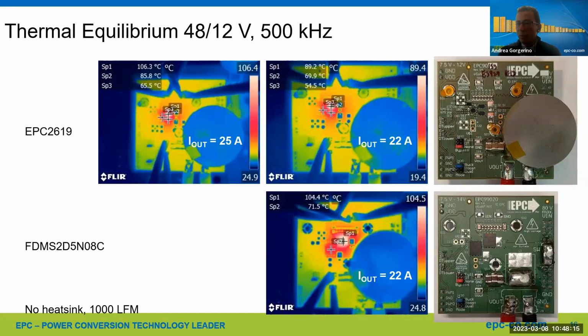They're much smaller in terms of all the capacitances, for example, which means you end up switching much faster, and the gate part. So I think the first challenge is just making sure you select the appropriate gate driver and controller. I already mentioned that, right? So you have to make sure you select the right part. And then it's layout. Layout is very important, because yes, you can make a bad layout, but then you're going to slow it down, and then you might as well use a silicon FET. So you want to make a good layout, and that's where I would say the biggest challenge is.